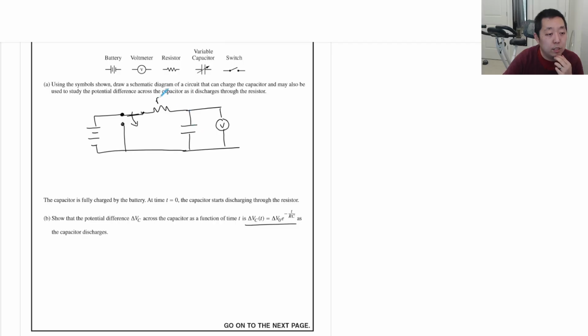Well, let's say this is R, this is C. We know when it's fully charged, the initial voltage on the capacitor, for t less than 0, or t approaching 0, right before we open the switch, we know there's no current flowing through the capacitor. So that means the capacitor takes the full voltage of the battery. We'll just say it's the initial voltage.